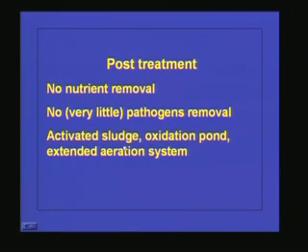So when we discharge it to the existing water bodies, what will happen? This reduced form of the minerals or the material will have a tendency to get oxidized. So definitely there will be an oxidation or oxygen demand in the system. So if you directly discharge the anaerobic effluent to a water body, there will be some BOD exerted by the treated effluent. So it is always advisable to go for a post treatment, which can take care of the oxygen demand as well as the nutrient removal along with the pathogen removal.